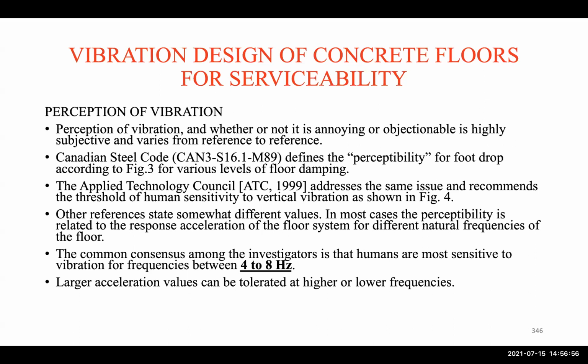So we have two figures here that show that. But the common consensus among the investigators is that humans are most sensitive to vibration of frequency between 4 to 5 hertz. Okay, 4 to 5 hertz. So larger accelerations can be tolerated at higher or lower frequencies.